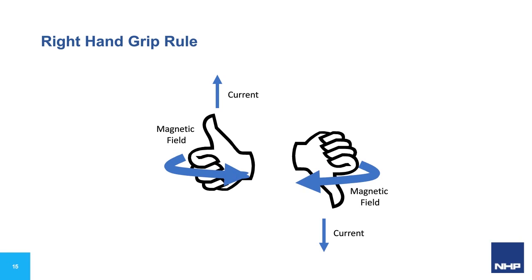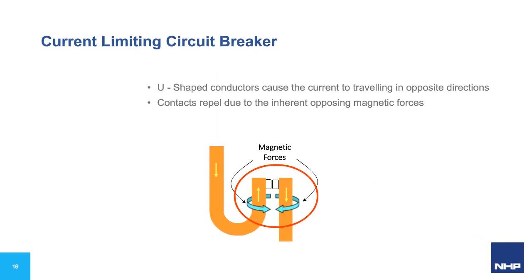In practical terms, the current limiting circuit breaker design relies on this area of physics to enhance its effect in the system under high fault conditions. The contact set, in some cases U-shaped contacts, in others specifically designed contact arrangements to amplify the effects, are designed so that under normal current carrying, overload, and events such as motor locked rotor currents, the magnetic forces are not high enough to actually force the contacts apart. Under short circuits at a medium to high level, the contacts will be forced to separate momentarily.